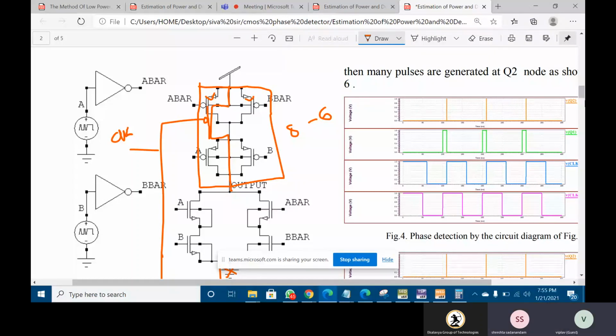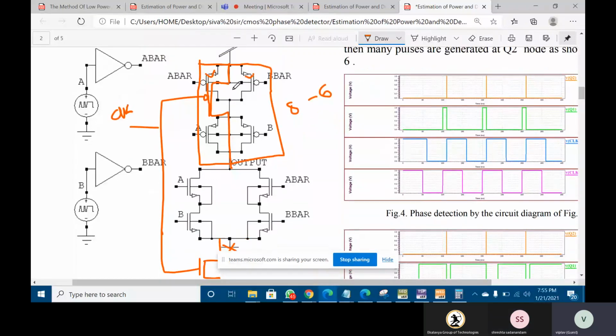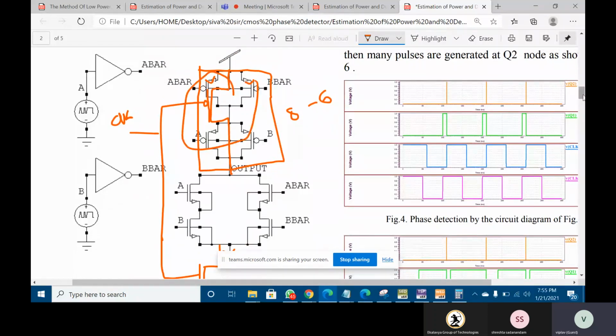One transistor, and these are 4 transistors, 5, and this is 6. So if we are having a huge circuit and we are designing with the CMOS, then the transistor count will also get decreased. So this is one of the advantages, that the count of transistors is also getting decreased over here. And also we have implemented this in 250 nanometer technology.